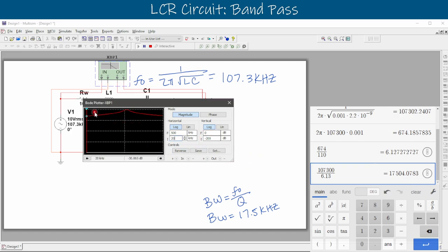There we go. So now we want to go to the middle of our peak, the very, very top peak here, and we'll watch our decibels on the bottom here. Our frequency starts off really small on one side, starts at 20, that's what we put it at right here, and it should go all the way up to 500 kilohertz. And if we run our thing all the way over to the other side, we see it stops at 500 kilohertz. So that's our scale. And so we want to examine when our center frequency happens, and we see that our decibels, this other number over here, is starting at negative 26 on this side here, and it goes smaller and smaller and smaller until it gets to about 0, and then it starts to grow again.